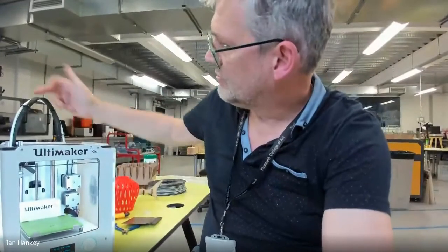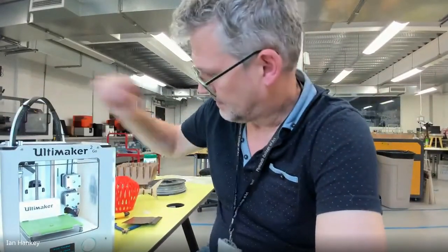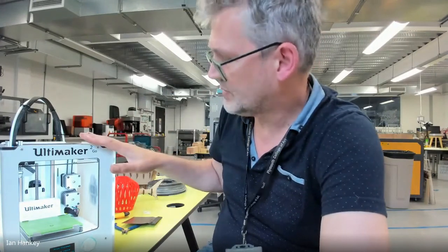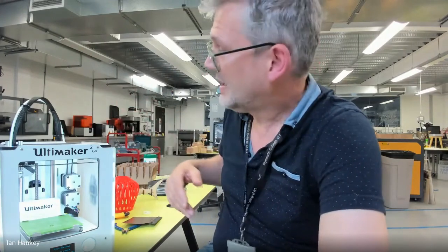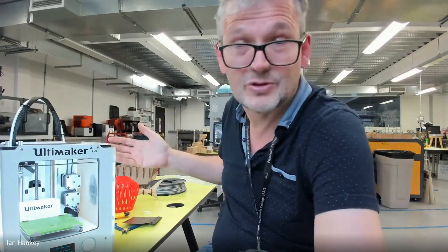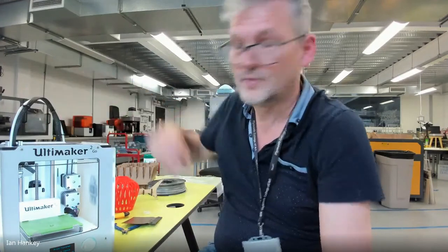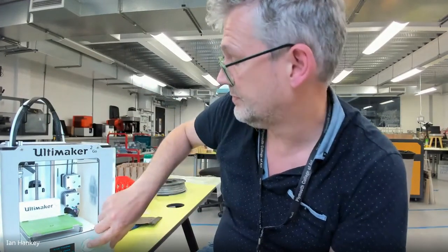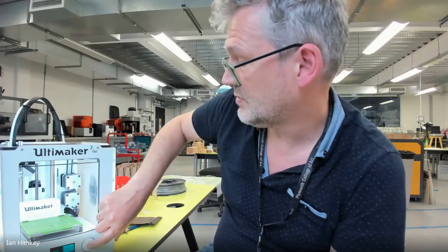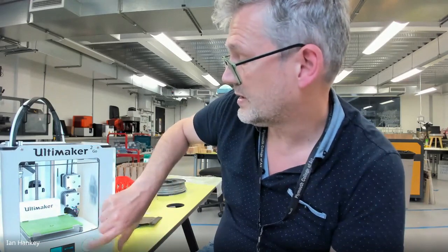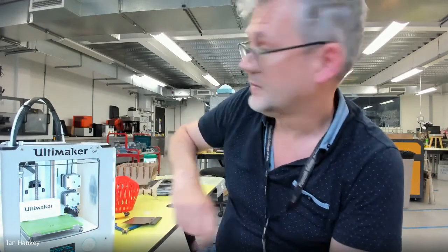Just as a matter of interest, this machine, one of the problems I had is that the material was left in the machine for a long, long time. So I tend to do this anyway, just with this one, but I tend to take the material back out of the machine every time I use it. And that way, it just seems to be indestructible. Every time you want to use it, it just comes through, it works perfectly. It doesn't get clogged up in there. So I'm actually going to set that now to remove the material. And we go to change, press the button, and that's going to heat up now and withdraw the material from the print head.